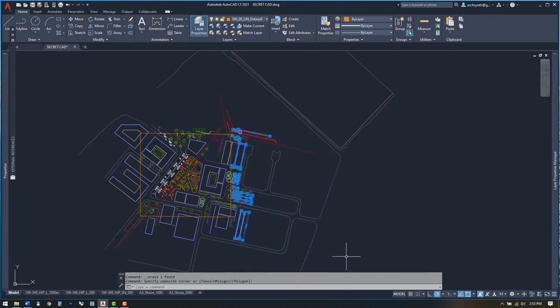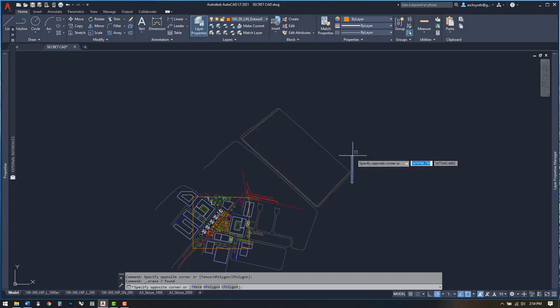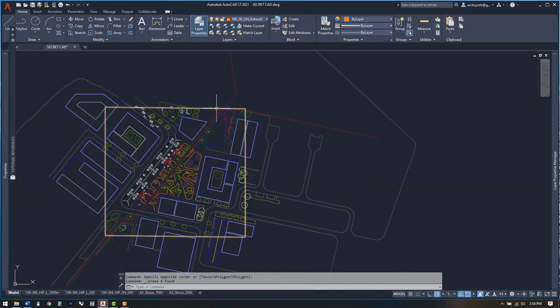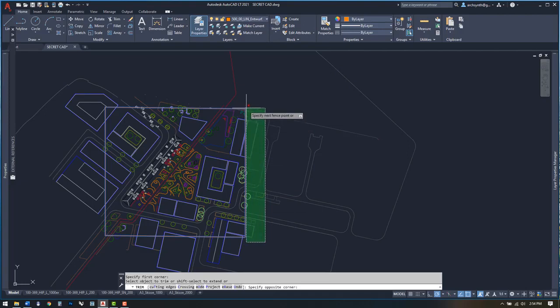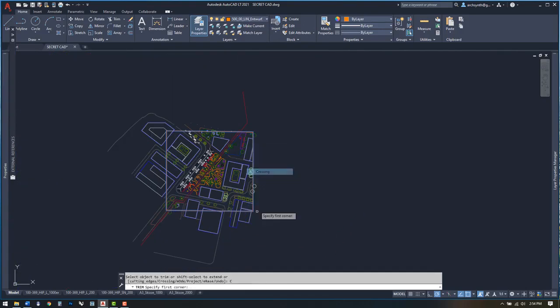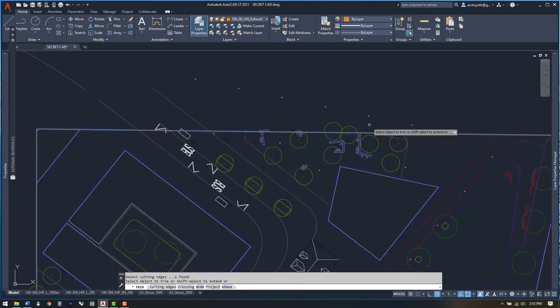Just like in Rhino, when we select from upper left to lower right, everything completely encompassed within the selection window is highlighted and can be deleted. If we go the opposite direction, we create a crossing window. Now we can turn this rectangle into a trim object. TR is the trim command. Then we can either draw a line through all of the objects to trim or right-click and select crossing. Either will work. I'm going to use crossing just for fun today. I'll speed this up and work between deleting objects outside of the boundary and using the boundary to trim.